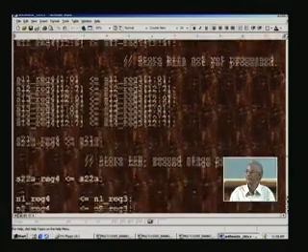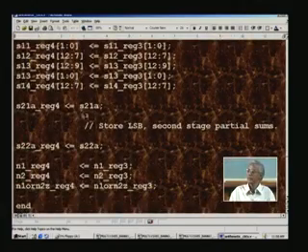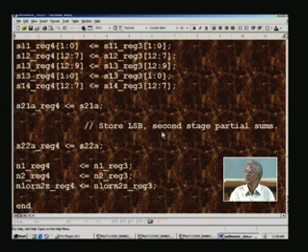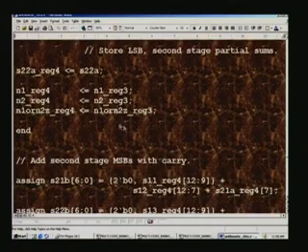So also S21A, which stores the LSB second stage partial sums. The LSB we have already computed in the second stage, and that partial sum is also to be stored, and we put it in another pipeline register here, and so is the case for S22A, which is the next output of the second stage. And we also should not forget the N1 and N2 sign bits, as well as whether the final result is 0 or not.